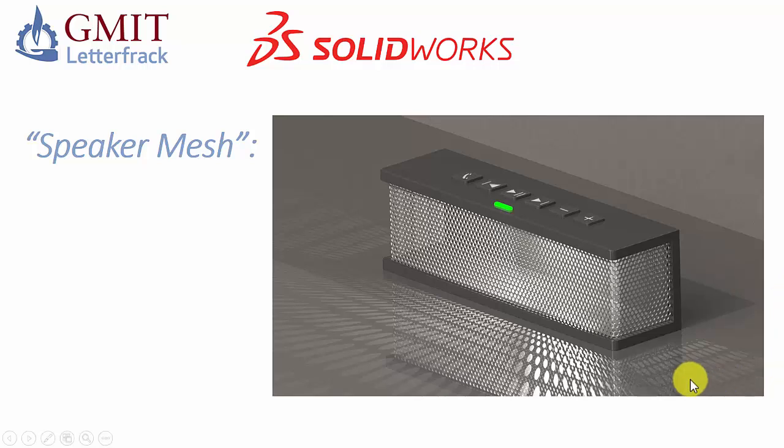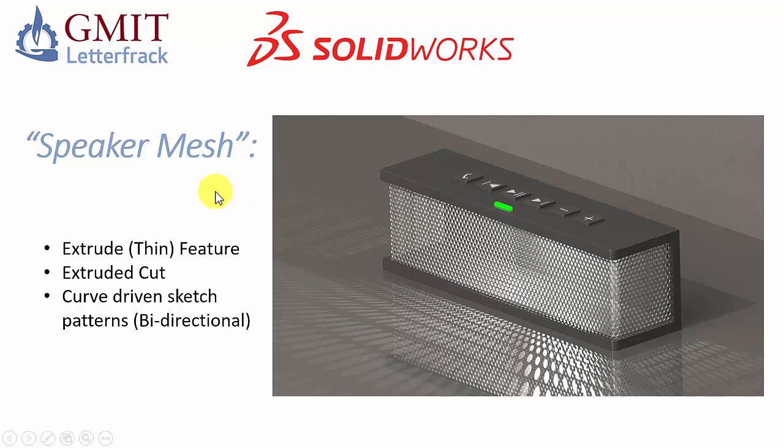But in this case I tried a number of different methods. I just couldn't get it to work. It seemed to be too complicated for a sheet metal part to bend it. So I've taken a different approach in this case. I'm going to use a combination of an extruded thin feature as well as a number of curve driven sketch patterns to generate the shape.